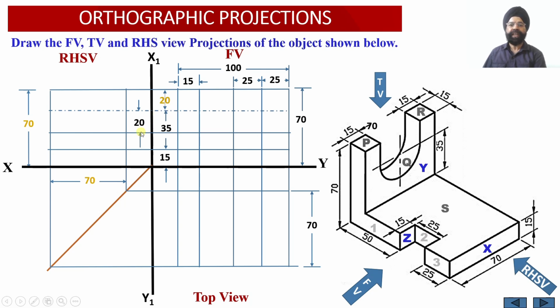Why have I drawn this particular horizontal line, or projection line, over here? The reason is that when I look at this slot from the front view, I will obtain a hidden line or dotted line corresponding to this portion of the slot. I could have drawn the dotted line right away, but I will project this dotted line once I complete the side view, because that will give me a better understanding of the U-shaped slot obtained on the right hand side, and only then will I draw the hidden line over here. But just for your reference, we have marked this distance of 20 millimeter from this center point; starting from this center, the radius of this circular portion happens to be 20 millimeter.